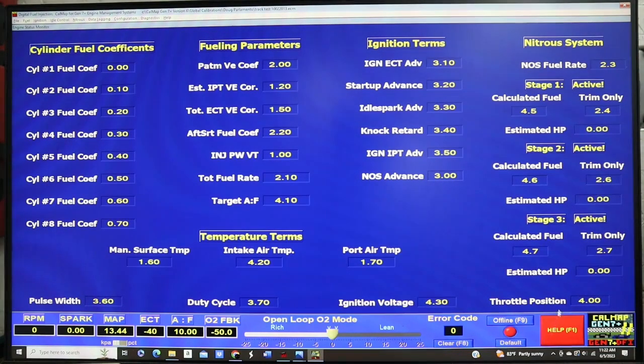your throttle position, you could actuate the pedal and you see 0 to 100, 0 to 100. Ignition voltage, obviously you need to have ignition voltage. The system will not work under 9 volts. So trying to start the car, the car's got 12.5 and you crank it and it drops down to 9 or 8.9 or something, slow cranking, the car's not going to start. And when you start getting the low voltages like that, you'll get voltage spikes, and that you could damage your ECU. So it's good to just check you have voltage before you get going.